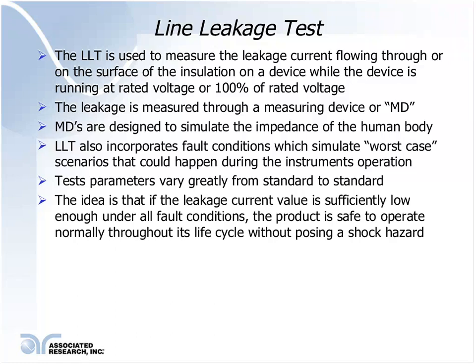Another aspect of the line leakage test that sets it apart from other electrical safety tests is the fact that it incorporates fault conditions. What are fault conditions? These fault conditions are designed to simulate the worst case scenarios that could happen during the instrument's operation. The three most common fault conditions are the opening of the neutral circuit, the reversal of the line polarity, and the opening of the ground circuit.